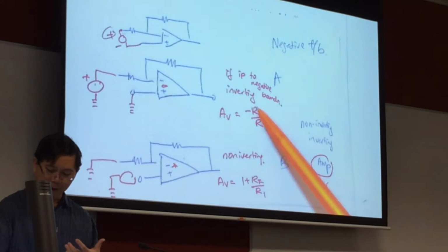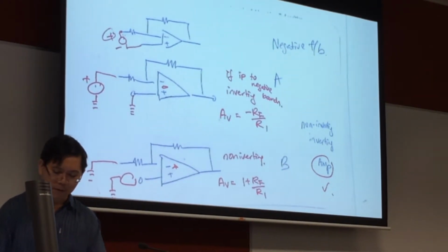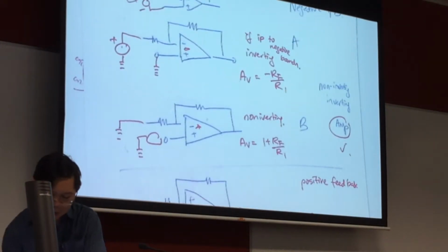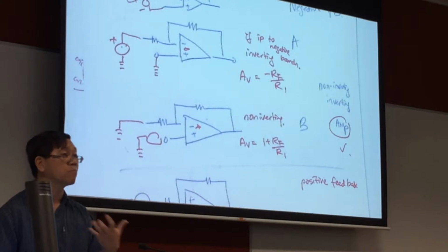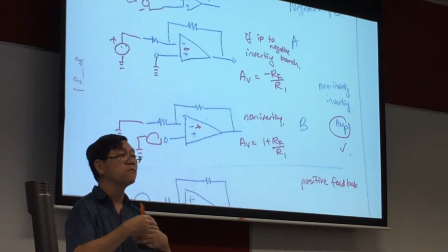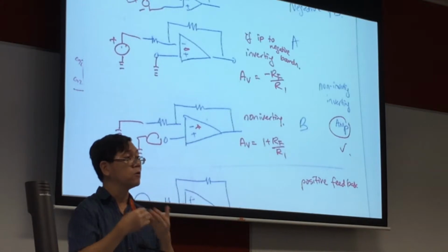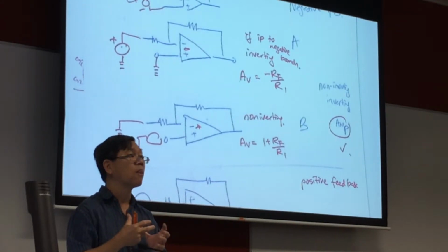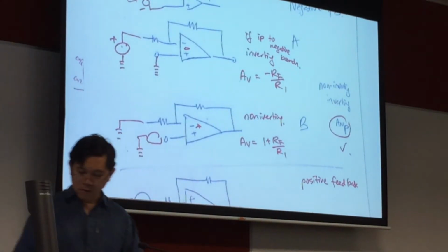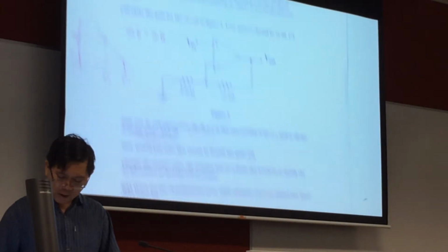This is positive feedback, right? If I were to, for example, connect my input down here, this becomes a non-inverting Schmitt trigger. And what is the advantage? You have a dual threshold. Having a dual threshold means it can be quite stable. It reduces the noise and glitches. If you want, you can read up on that, which is basically covered here.